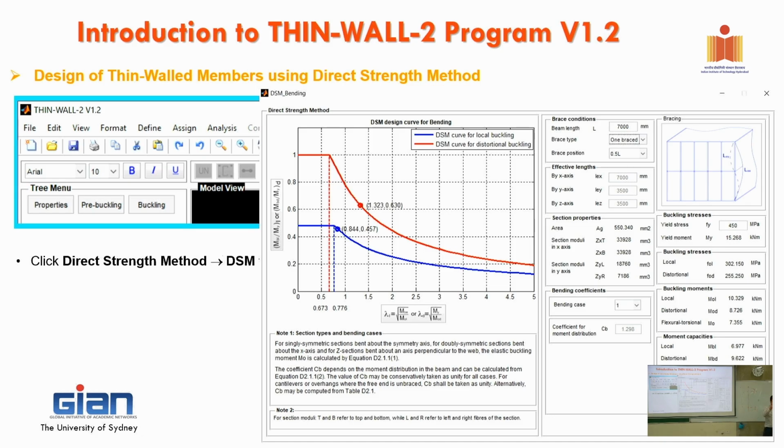And that will give you an idea about what is different here. In shear analysis, remember structure analysis, this is shear flow. So when you add them up together, it's not in equilibrium, isn't it? If it needs to be in equilibrium, what is it going to be balanced with? Moment gradient. So that's why we're not going to do this one with the moment gradient. But the beauty of finite strip is we can isolate it.